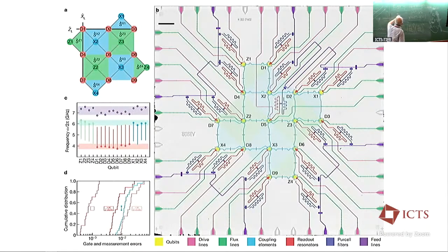So the rule is, loss means moving poles, just like we've seen in other talks. Poles in the left half plane mean actually loss. Poles on the axis, this is in the Laplace plane, mean no loss. And poles on the right-hand side are unphysical. They correspond to growing values. And that was indeed the basis of some discussion.